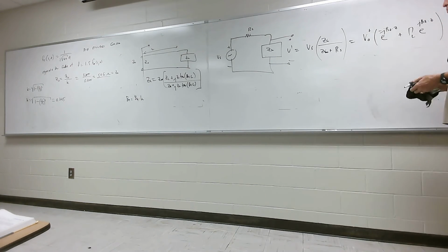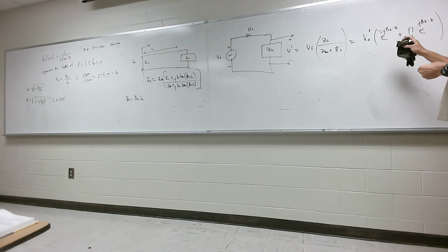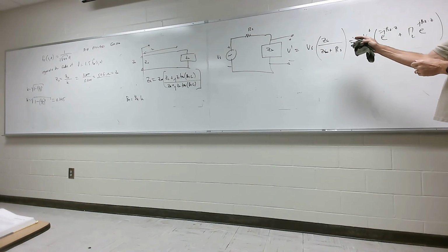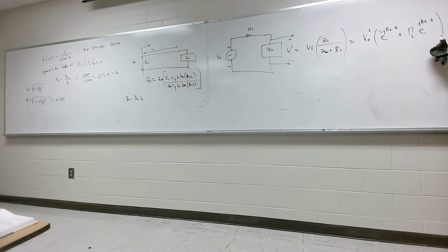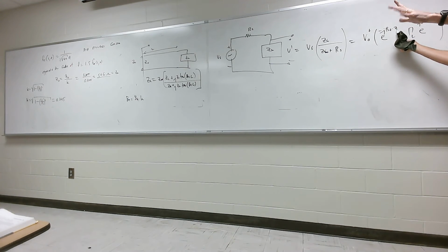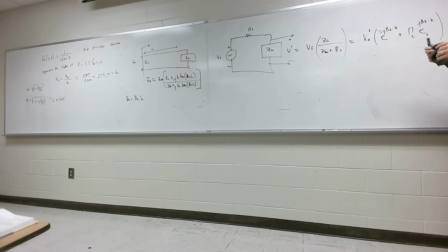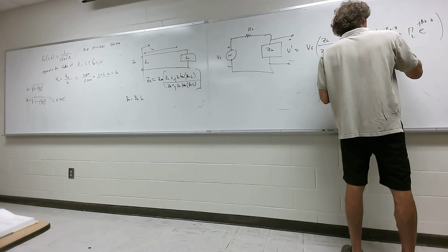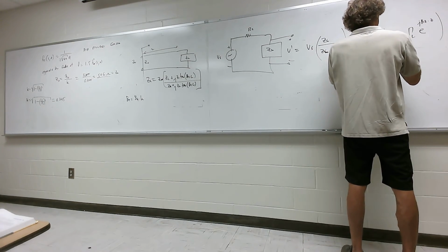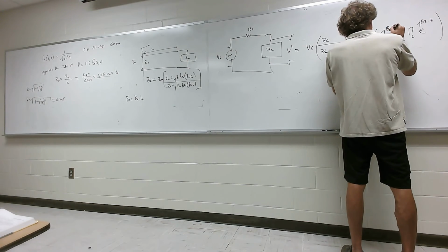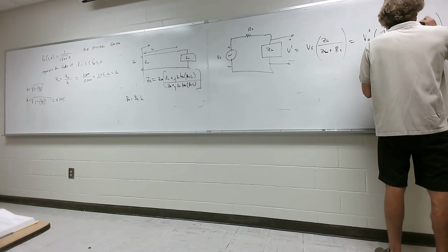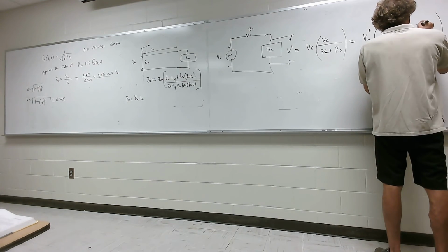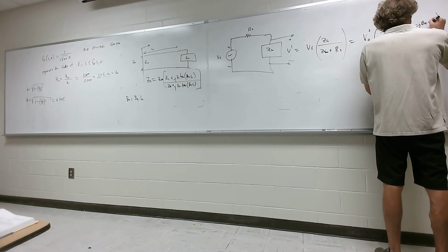Now that's the general form, but we're at z equals minus L at this point. Y'all follow me? You remember this right here from transmission line theory? Same exact thing. Now here's the one difference. z here is going to be minus L, because we're at the place where the signal is actually fed into this. So now this becomes a plus, and this becomes βz times L, and that becomes a minus. And this becomes e^(-jβzL).